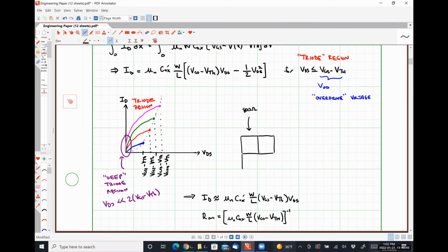But if I were to do something dumb like this, that's actually just one square. It's just bigger, so it's still 800 ohms. So anyway, the sheet resistance of a section of N-well material is 800 ohms. The sheet resistance of high resistance polysilicon is usually on the order of somewhere around 1.1 to 1.2 kilo ohms per square, etc. So we have to make things physically large due to the design rules to get large resistances.